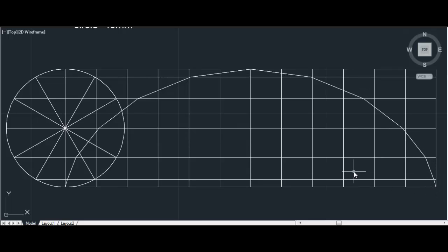Now it is time for you guys to hear why I followed this procedure. Basically, if you open up the circle, it will be a straight line of length equal to the circumference. And I divided the circle into 12 equal parts to get each and every location of the point whose cycloid is to be drawn.